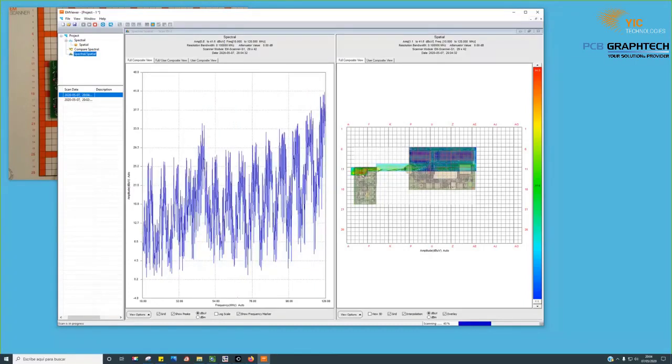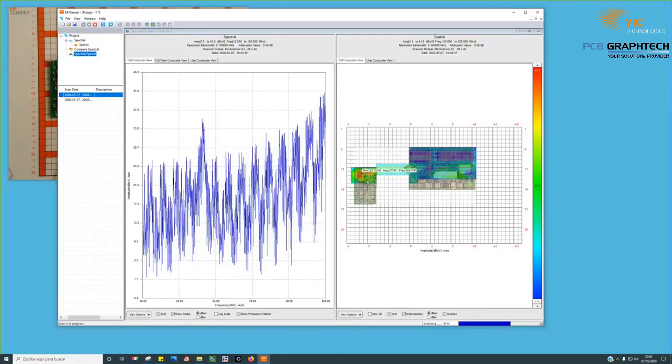Remember that the DC-DC converter is switching, I don't know, at 100 kilohertz, 200 kilohertz, but it's very typical to obtain from this kind of converters EMI that can create failures in radiated emissions between 50 megahertz up to 200 megahertz, for example. This activity is coming typically from ringing in the switching activity of the transistor or the diode, or from some kind of parasitic oscillation that you have created in the layout of your PCB. This kind of analysis is very useful to identify exactly where you have these problems.